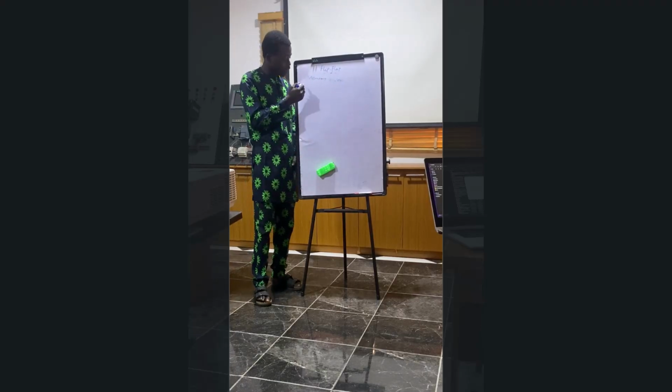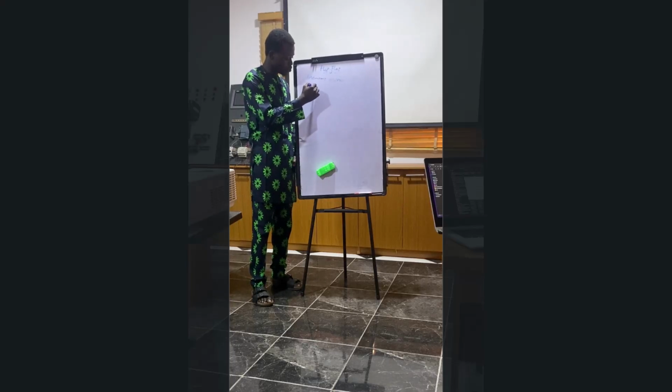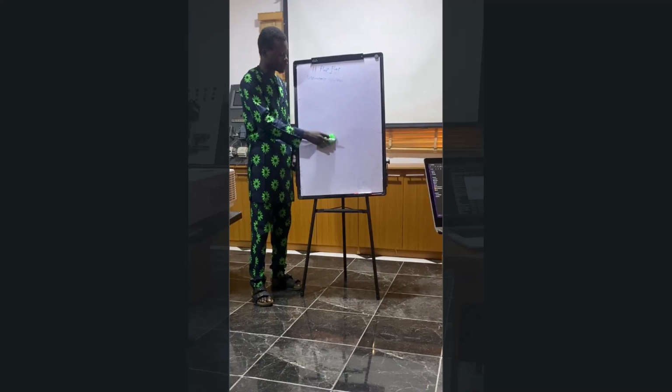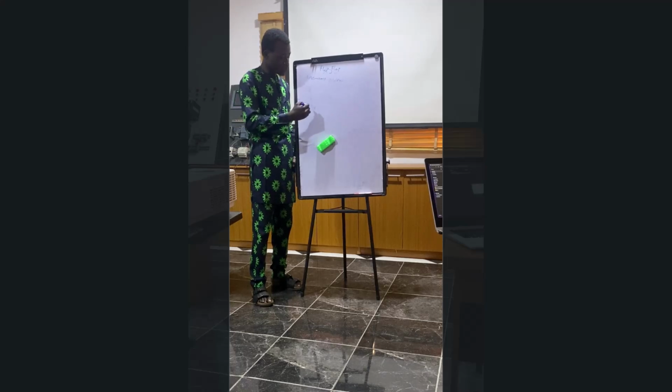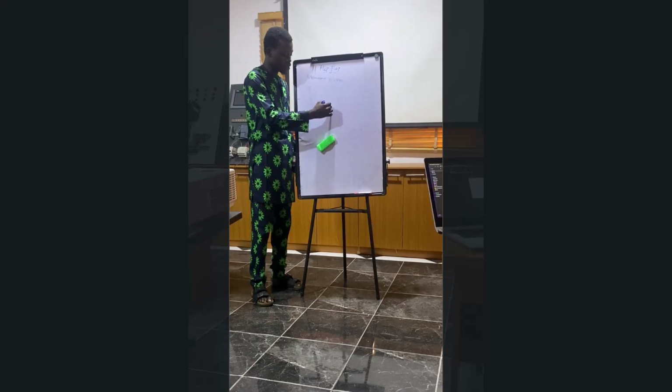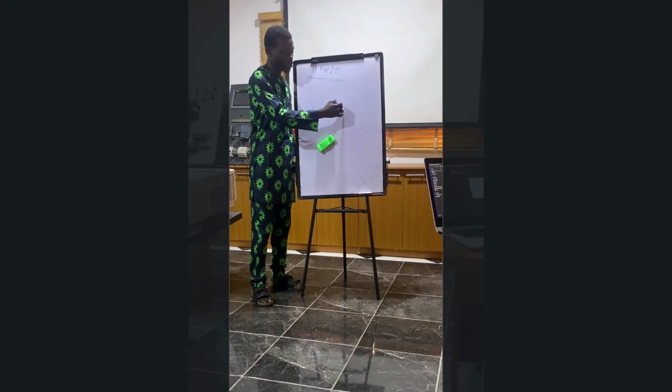Just as I was talking about the input addresses and the output addresses, we also have the memory addresses. So you have the bit memories, which you'll be seeing as something like M0.0, M0.1, which are for bits or Boolean signals.